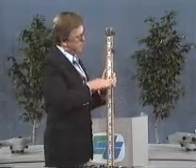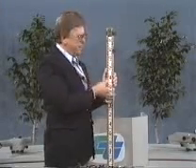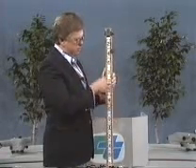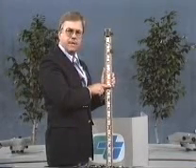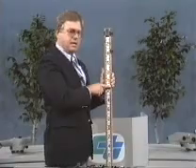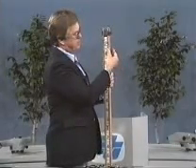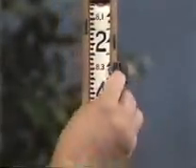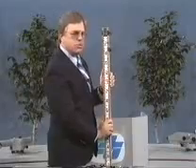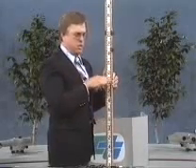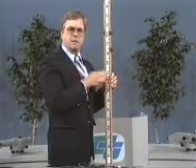So when the line of sight was down here, this tape would be rotated to read 910 right here on this tape. Once that is read, it can be locked in position with this little lock on the side of the rod. When that is locked in position, now when the front portion moves, the tape doesn't move. So that elevation is always locked into the rod at that point.